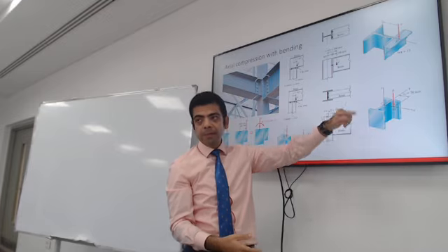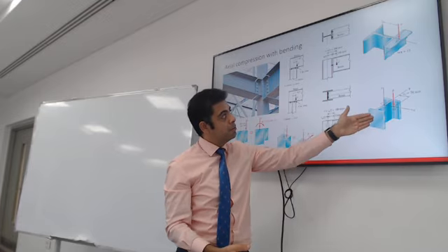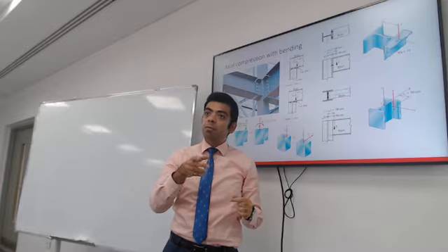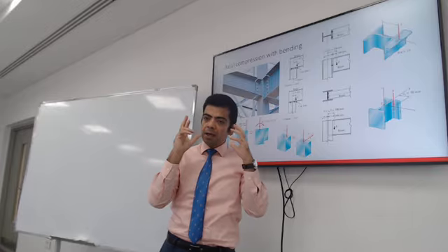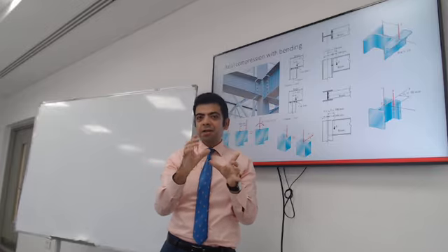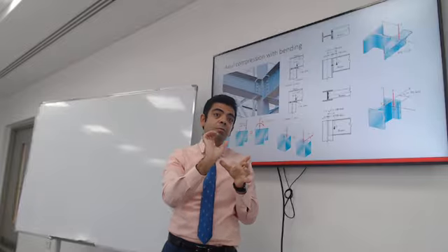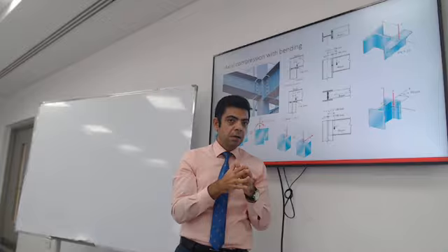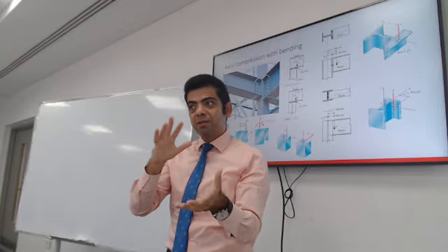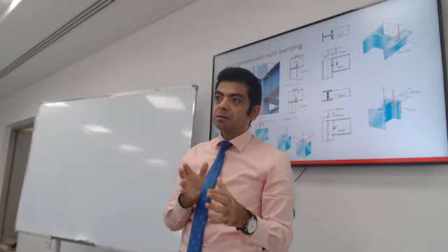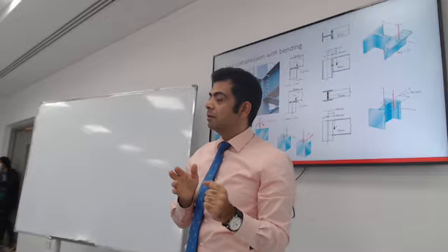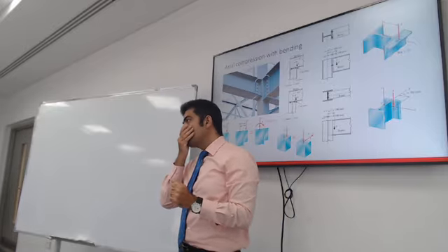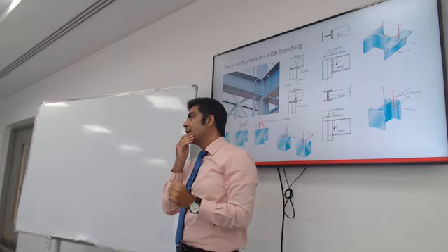about y. And if there is a second beam framing in the y direction, it will create a second moment about the x-axis. Can you visualize a cross-section that is exposed to moment about x and moment about y? Does that make sense? How would a section resist moment in two directions? Squared. What do you mean squared? The cross-section of the column is squared.